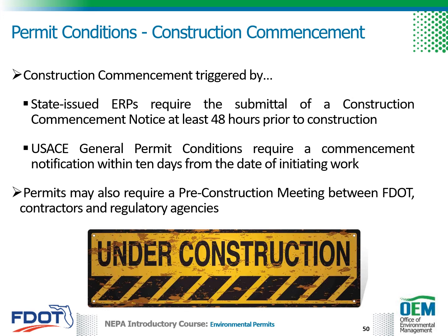Rule 62-330.350 FAC requires that the permittee fill out the construction commencement notice form at least 48 hours prior to starting work. This form is generally submitted to the Water Management District via e-permitting or emailed to FDEP. U.S. Army Corps General Permit conditions require a commencement notification within 10 days from the date of initiating the work authorized by the permit. This notification is submitted by the contractor with oversight of the CEI.